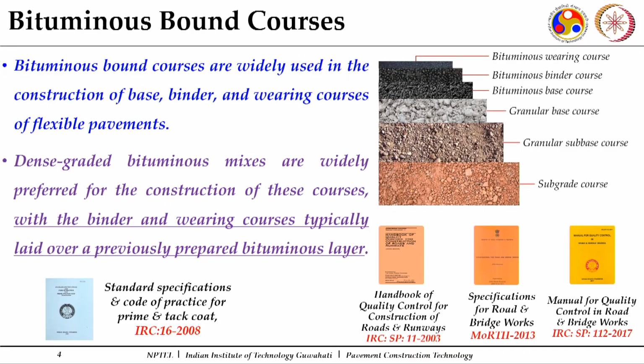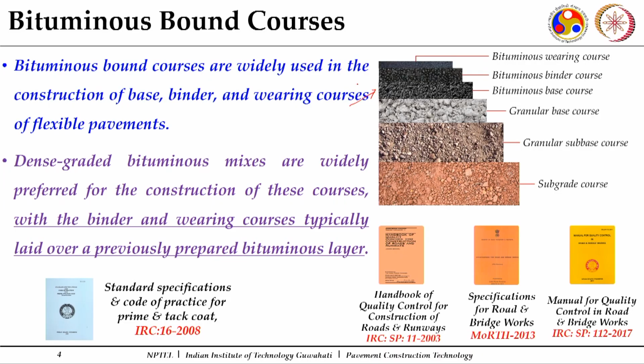Now, as we have already discussed in some of our previous talks, in flexible pavements bituminous bound courses form a vital role specifically, and they are widely used in the construction of bituminous bound base courses, bituminous bound binder courses and bituminous bound wearing courses. So, these are the three typical layers in which these bituminous bound courses are used. You have bituminous base course, bituminous binder course and bituminous wearing course or the surface course. And the binder course is the one which comes in between your surface course and a bituminous bound base course.